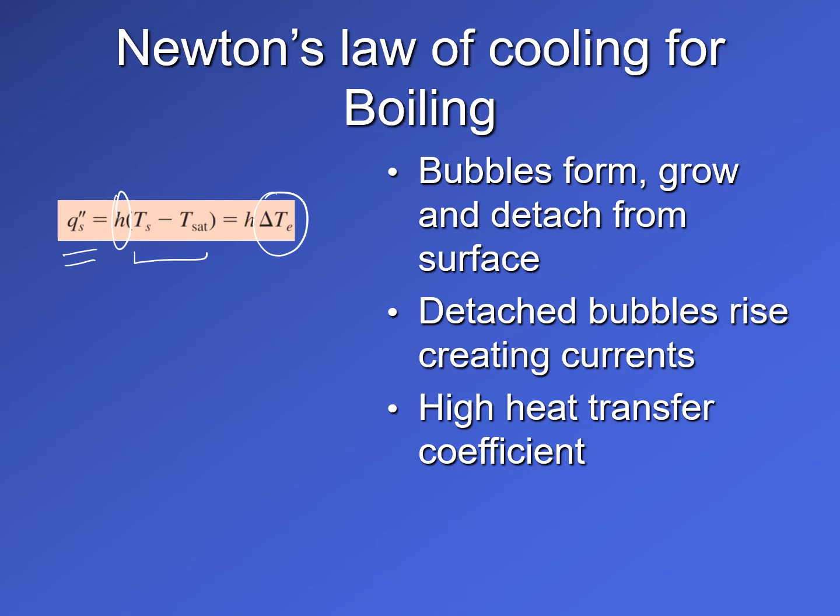You may have seen that when you're boiling water, the whole water starts to mix vigorously, and this large amount of mixing in the fluid is responsible for high heat transfer coefficient, because one, the bubbles are taking away a lot of heat from the solid, and the whole idea of convection is that the heat transfers from the solid into the liquid. So these bubbles in the process of forming, they take a large amount of heat because of latent heat. So that is one, and then as they rise up, they take this heat away, or this energy away from the surface, and the energy gets released on the surface as vapor.